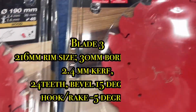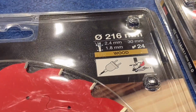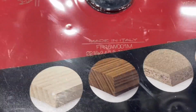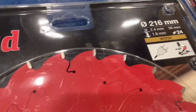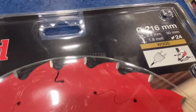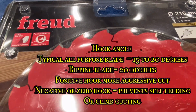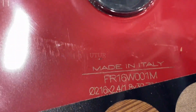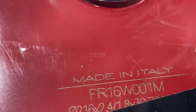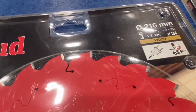The third blade is an interesting one. It's got a 216mm rim size diameter, a 2.4mm kerf, and it's 24 teeth with a 30mm bore center. It's got a negative hook or rake angle of -5 degrees, which means it's perfect for table saws, radial arm saws, and miter saws, as the hook angle prevents self-feeding or climb cutting, which necessitates adding more pressure to feed the workpiece.